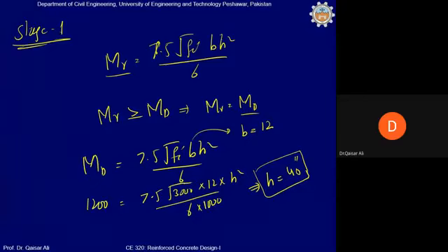And how to calculate that reinforcement? That reinforcement can be calculated corresponding to stage 2, or you can also calculate the reinforcement corresponding to stage 3. In this course, we will design the beam corresponding to stage 3. However, just for understanding purpose, for this example, we will also calculate the design reinforcement in the beam corresponding to stage 2. Clear? तो हम क्या करते हैं?